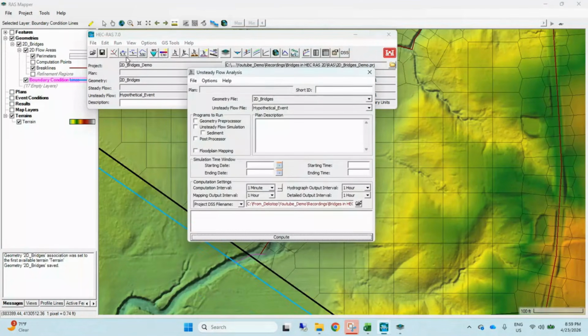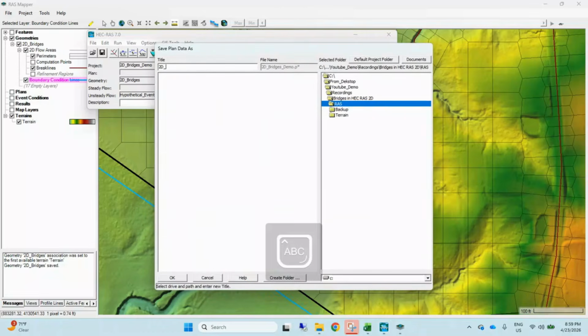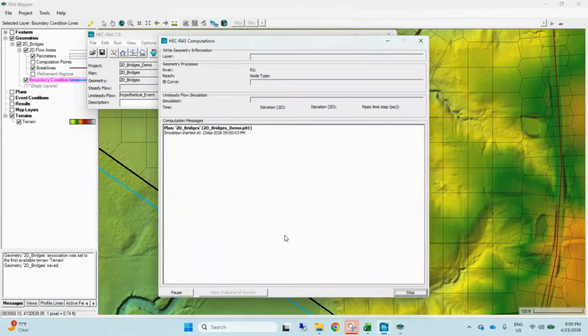The final step is setting up the plan. Since this is a 6-hour storm, a 24-hour simulation window should be enough. At this stage, we are simply checking that the model runs cleanly without any issues, which is the main goal for now. A good modeling practice is to begin with a simple setup and add complexity incrementally, which makes troubleshooting much easier later on.